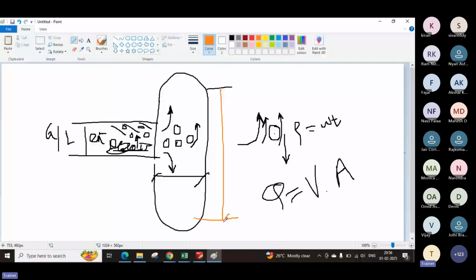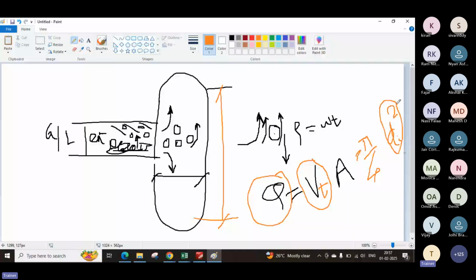That will give you the sizing of the separators. So you know the terminal velocity we require to maintain the separation, that is the Vt. So area is nothing but pi by 4 d square, that is the inlet diameter, and you know the gas flow rate. You know the Vt from the equations, then you can find the diameter of this one. And how to estimate the length, we'll discuss in the next few things.